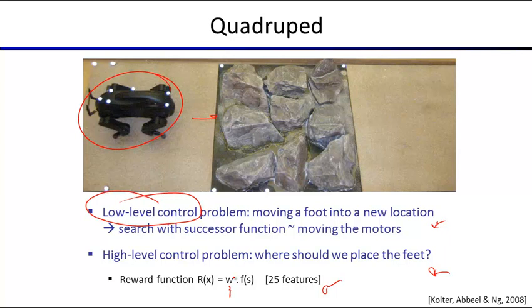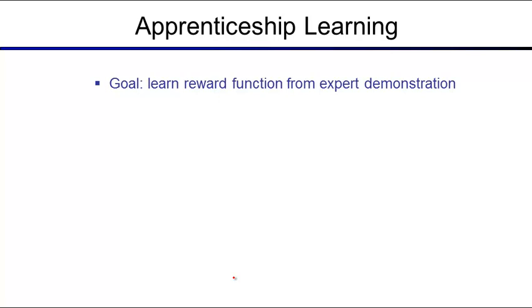That's a lot of weights to choose. You can try to tune them by hand. We tried. It's actually really hard to get those weights in a good position. So we said, well, let's learn those weights. Let's do machine learning to find the reward function. So rather than machine learning to find a policy or a trajectory, machine learning to find the reward function. The reward is of this format. We've done a lot of learning of this format, some weights times features.